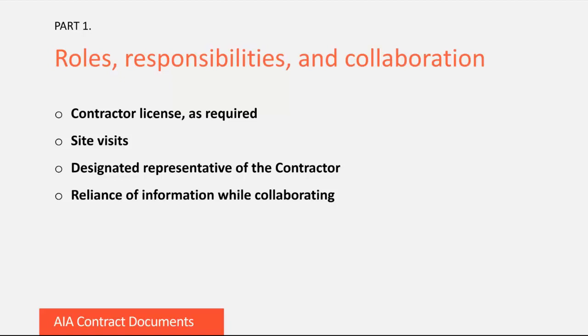One of many responsibilities of the contractor at the start of a project, and ideally prior to it, is to take any measurements at the project site, visit the site to become familiar with conditions, and compare your observations with the contract documents to verify any discrepancies. In doing so, if you find errors, omissions, or inconsistencies with the drawings or specs, these can be brought to the attention of the owner and architect or engineer, even the construction manager's advisor if one is on your project. Generally, owners appreciate the communication, being informed of any issues like this up front, and preventing bottlenecks down the road in terms of ordering materials, how the work is carried out, or time and cost changes.